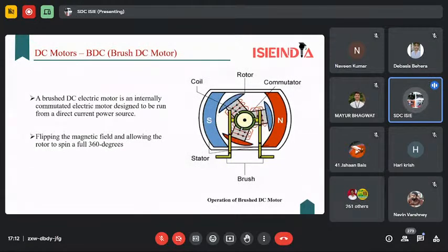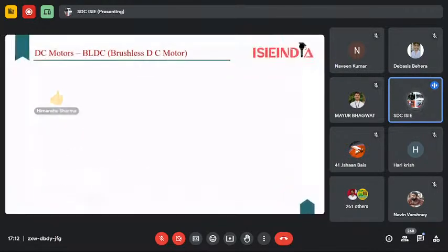And this is a permanent magnet DC motor, which you can see in small appliances like a toy car and many accessories available in your hand, like a trimmer and many clocks. But you can see that the major problem we are facing is the brushes, because over time carbon deposits are created in the brushes, which can decrease the lifespan of the battery. And we can't provide an external power supply for the armature winding at the time of movement. So we come to the brushless DC motor.